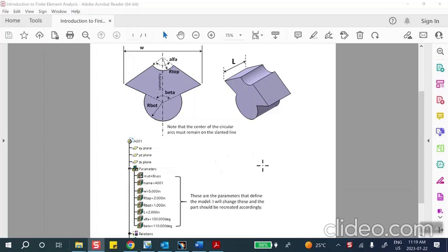Now, the only comment that I have here is that notice that on the very top you have material equal to base, or MAT equal to base. When you start the part, before you make absolutely anything, you can put a material on it. And when you do that, immediately it creates a parameter for you. The name of that parameter that it creates by itself is M A T E R I A L, material, starting with the uppercase M. So you just apply that material and you get this first line, except that it doesn't say MAT, it says material. You can go and change the name of it as I will show you.